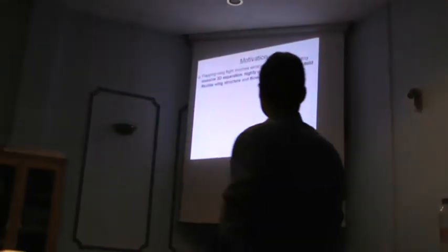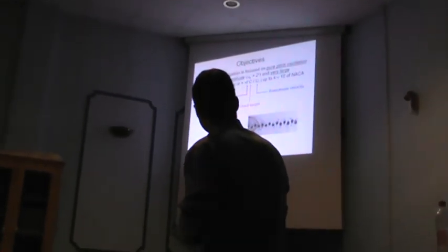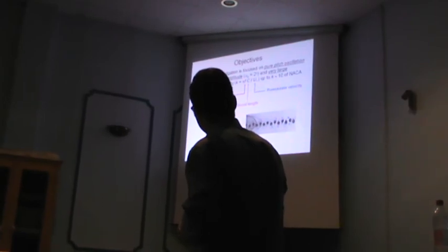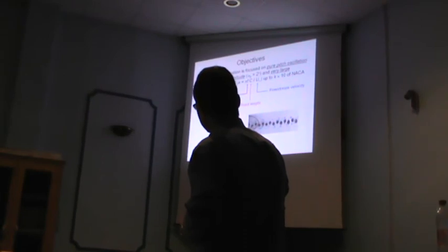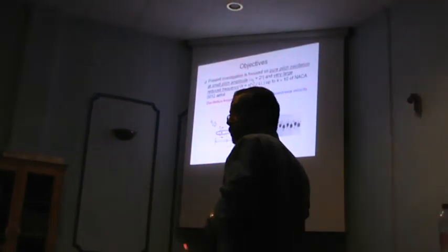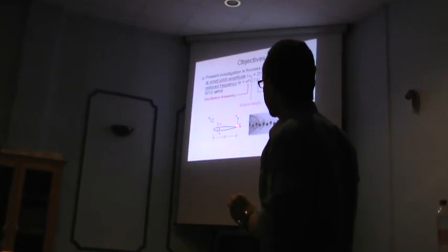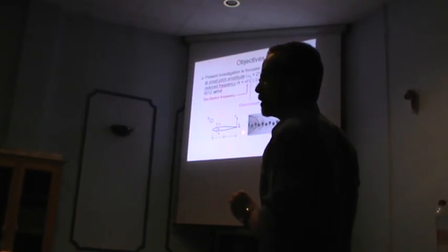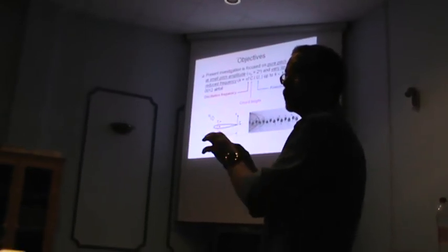The research we are working on now, we are actually focusing on exactly this part. We're using whole field measurements. With high resolution measurements, as the airfoil oscillates, we're looking at the details of the boundary layer, how it separates and how it rolls into the vortex structure. Our aim is to hopefully understand the physics of vorticity shedding and how this vortex flux maps into the vortex pattern and relate this to the motion of the airfoil.